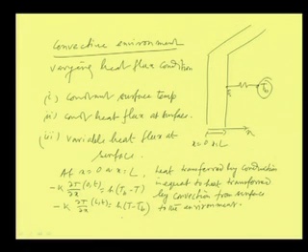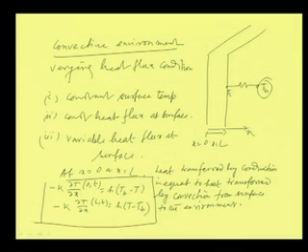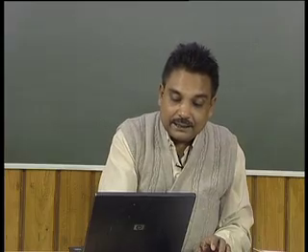For this surface it is a positive x, for this surface it is a negative x. So that negative part of del T by del x, and the minus sign, takes care of it in this equation, and then it becomes h into (T minus T_b), and heat will be transferred from this side to this, and in this case from this side to this. But anyway, this is a general form of the cases when heat is being transferred from one surface to the other by a combination of conduction and convection mechanism. So, this becomes the boundary conditions.